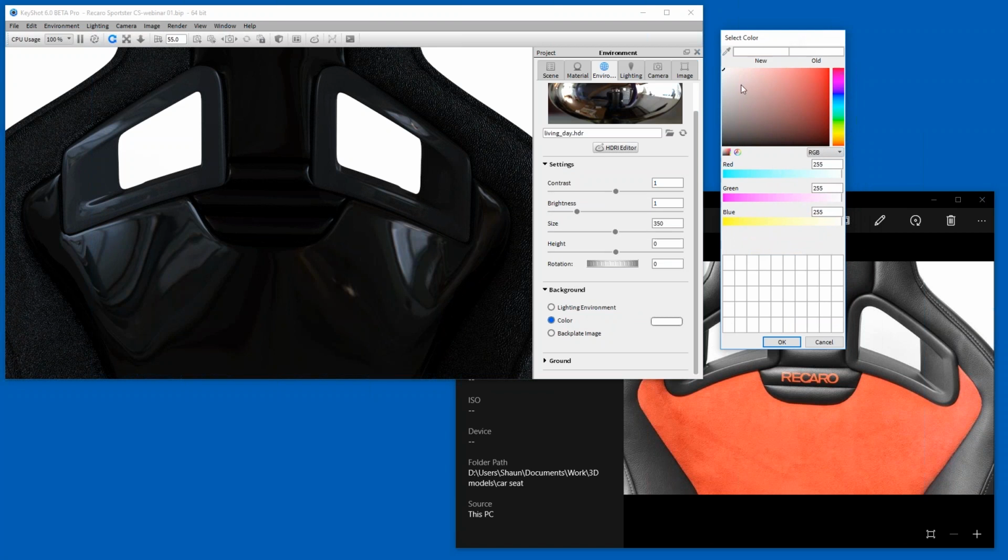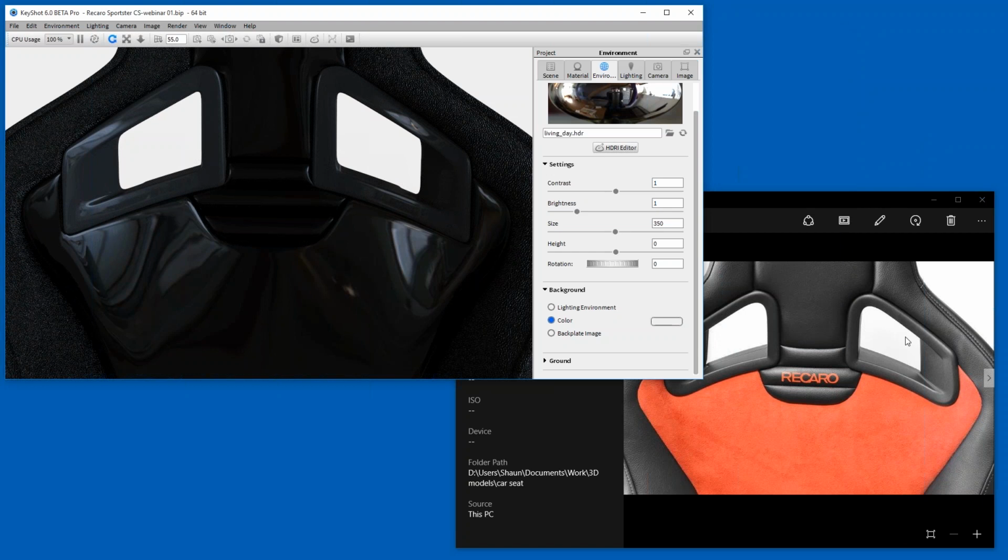Nothing in the real world is absolute white or absolute black. So a good thing to do is, when you look at anything that has a white value or a black value that you want to use, open up the color panel and knock it back just a little bit. Just by knocking it back a little bit, maybe adding a little warm tone to it, it adds a touch of realism to your scene. As you can see, this has a warm white tone to this background as well, and it adds a little bit more realism.